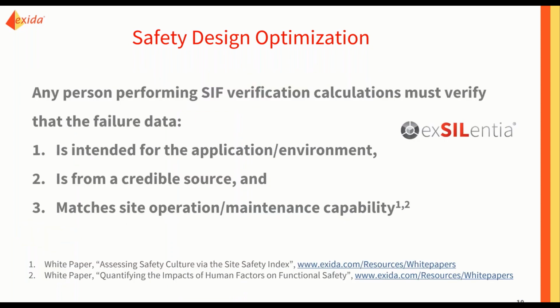Therefore, we have imperfect devices that have failures we can't practically eliminate. In many cases, they're unknown to us at design time. So we will have DU failure rates in the different devices we use in our safety instrumented functions. But it is absolutely possible to have good, credible failure rate